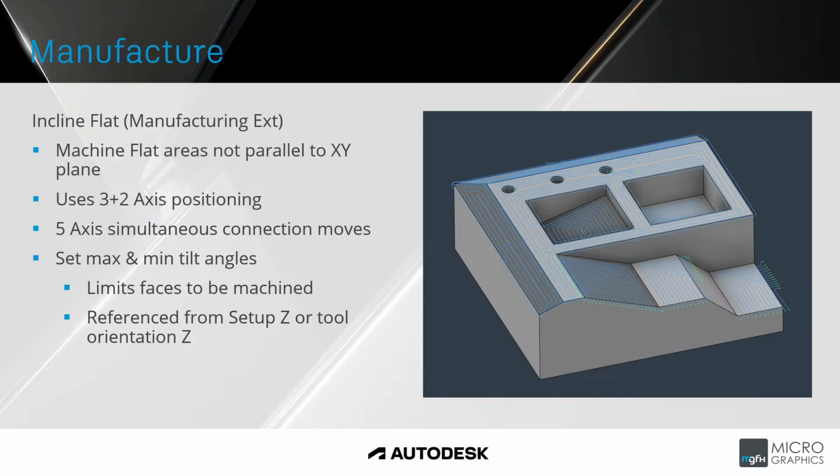Now on the tab for your 5th axis settings, you are able to include the ability to machine inclined flats. So this will find surfaces that are not parallel to your XY plane, or should I say surfaces that are not perpendicular to your Z axis. It will use 3+2 positioning to position the workpiece and then do the flat machining. The connection moves between the flats are 5-axis simultaneous.